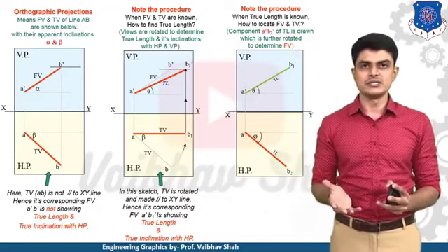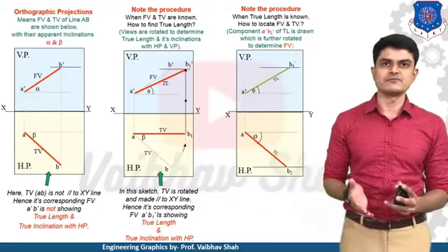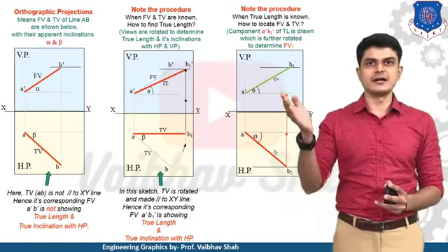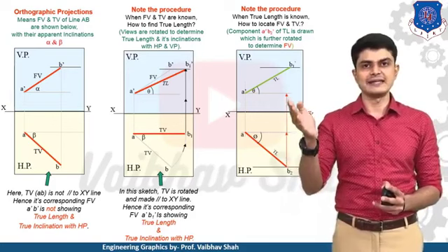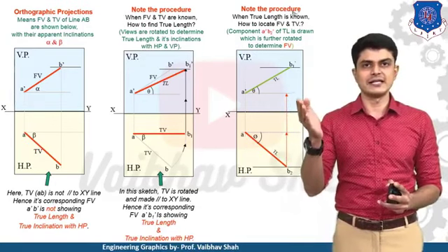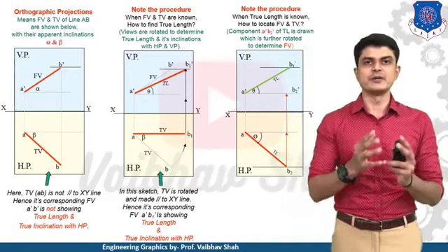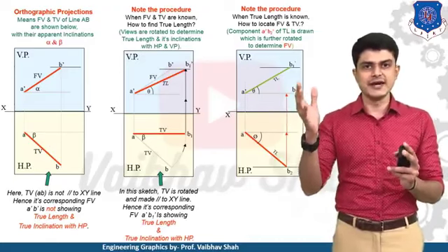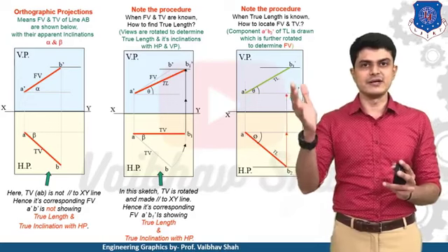Then we'll draw a straight line from this point B2 until we reach the A dash horizontal line, and mark this point as B2 dash. Then we'll set our rounder with A dash as a center and A dash B2 dash as a radius.